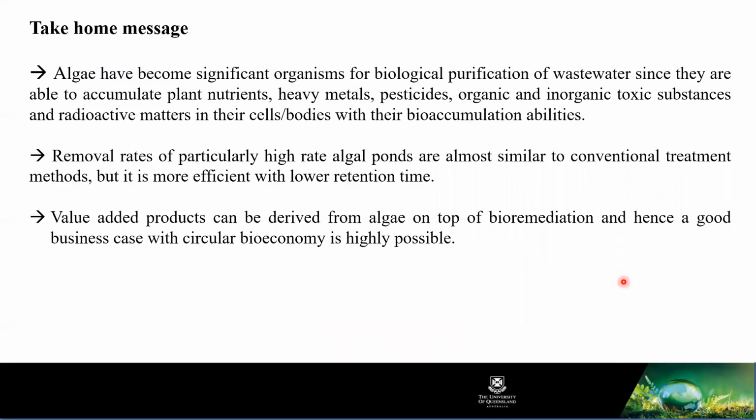So what is the take-home message? We are nearly at the end of the presentation. Algae have become a significant organism for biological purification of wastewater, since they are able to accumulate plant nutrients, heavy metals, pesticides, organic and inorganic toxic substances, and even radioactive matter in their cell bodies with their bioaccumulation ability. That's one of the take-home messages I would like to tell everyone listening to this lecture. The removal rates of high-rate algal ponds are almost similar to the conventional treatment method, but it is more efficient with lower retention time.